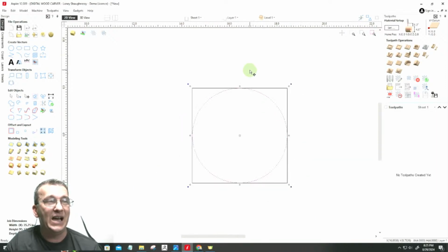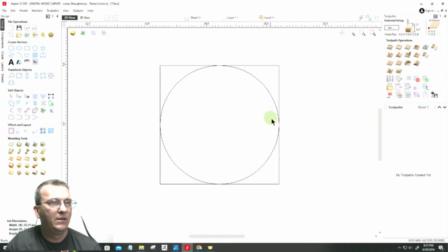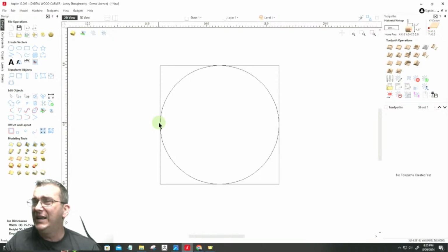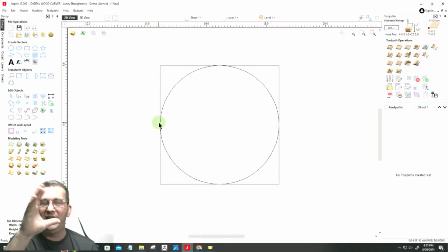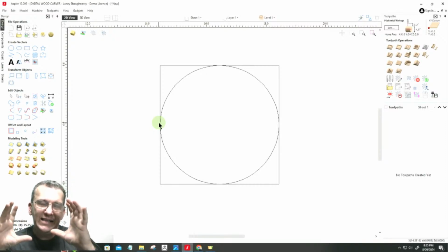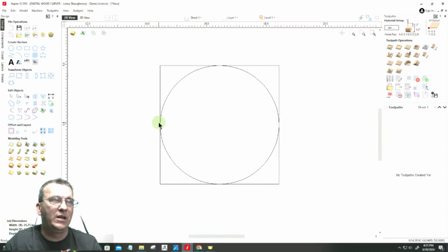And that's not going to be the case, because if I do that, I'm going to end up with a flat spot here, here, down here, and over here. We need to account for that somewhere or another. We need to take our cylinder, our finished diameter when we're rounding, and it needs to always be slightly less than our blank.